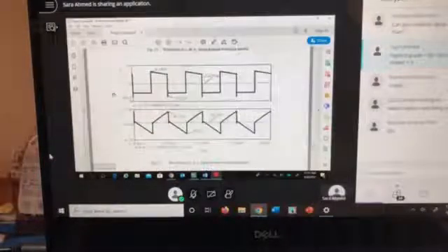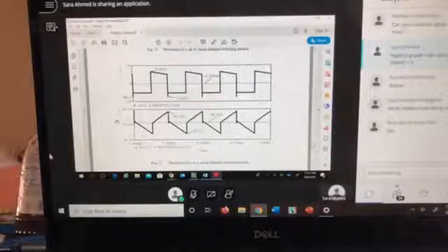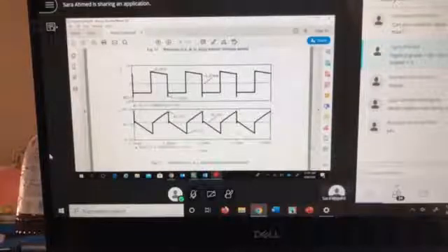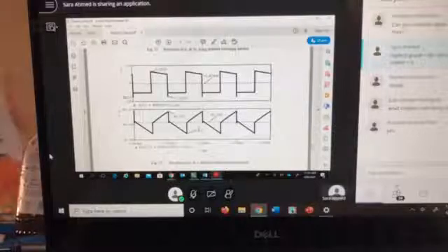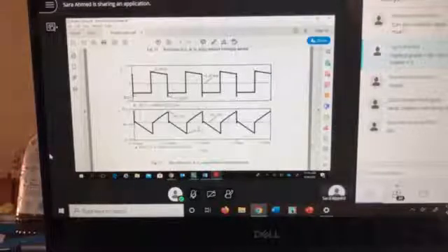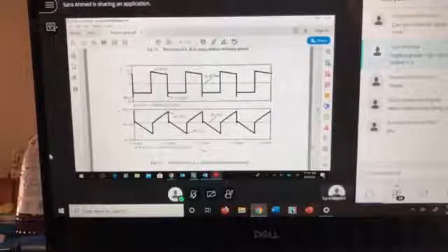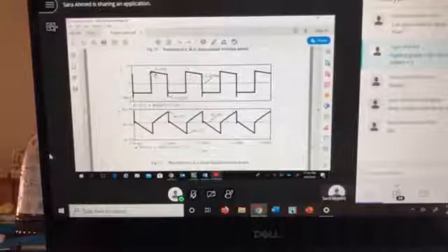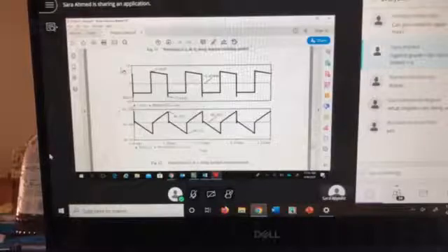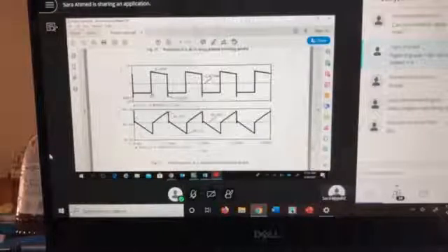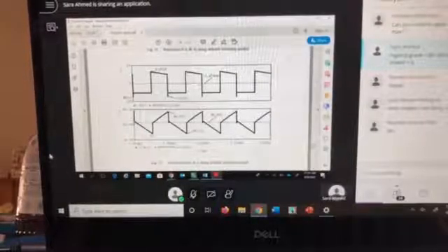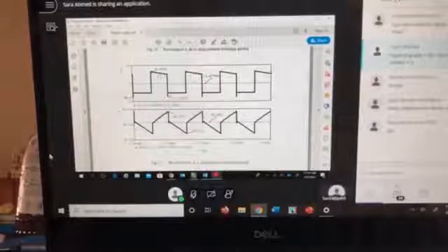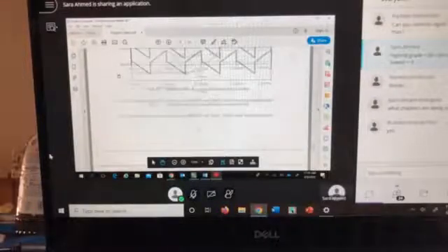Then IC and V out is the same thing. Your output voltage, you're showing me that it's regulated or controlled by the duty cycle to 48 volts. And your current is basically I of C here that corresponds to this output voltage, right? So again, what is the I of C? I of C is C dV by dt. So the slope is coming from how your voltage is changing. If the slope is negative, then the voltage is going down. If it is positive, then the voltage is going up.